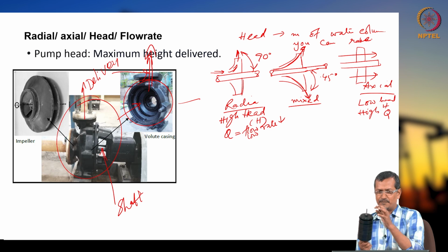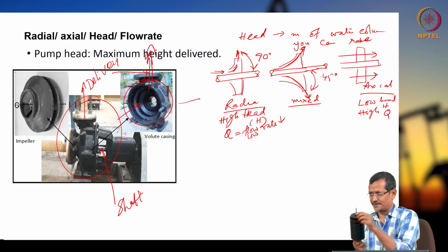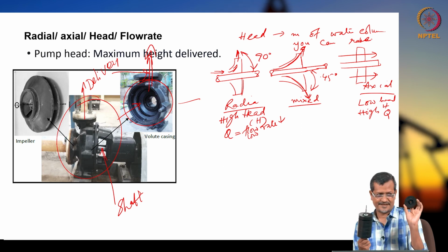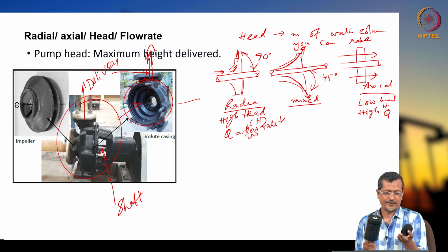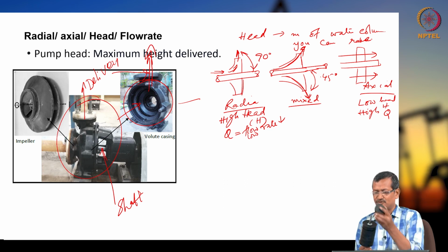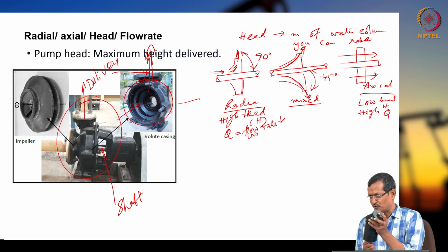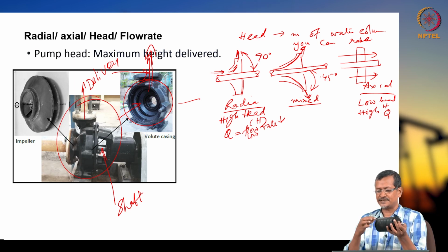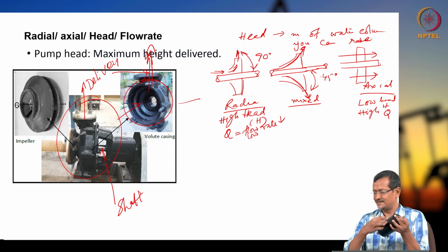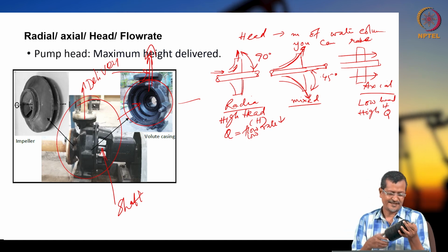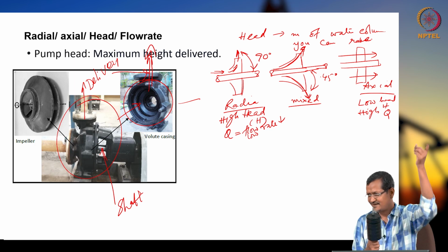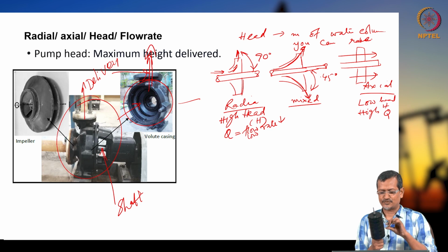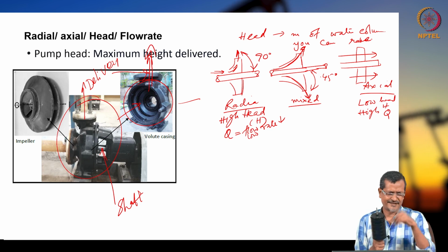Okay. And one impeller, one stator, or rotor, and this impeller is the rotor also. Impeller or rotor, it will be rotating. The stator is not rotating, so all the impellers will be rotating together, and you are delivering fluid. So how much total head will it give? Let's say one stage delivers 1 meter. So with 6 stages, I have 6 meter total. If I have 100 stages, I can develop 100 meter head. So simple calculation, fine. You can remember, like one stage developing 10 meter, so 100 stages, 10 into 100.